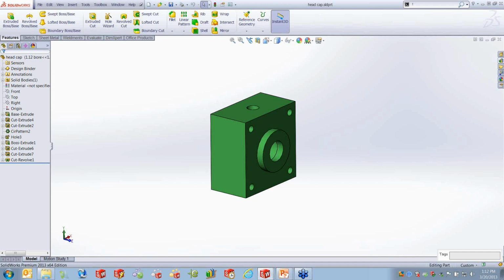So if they're floating in space, it's fine. Now, you can't have that because components will move all over the place. Someone can actually grab it. But the example, can a bolt still spin? Absolutely. If you put a bolt in a hole, there's no sense putting a third mate on there to lock down the rotation. Leave it there. Adding that extra mate is going to slow it down.